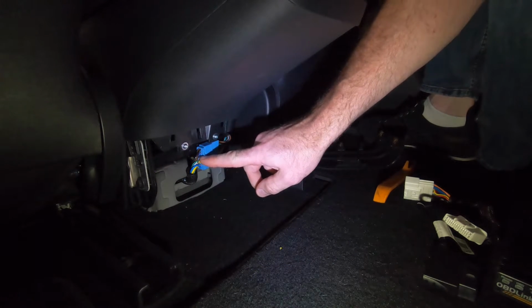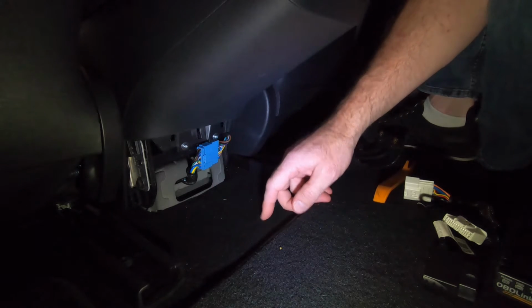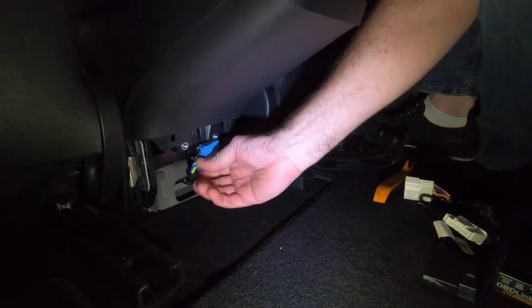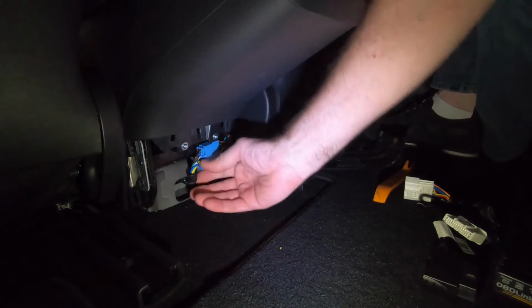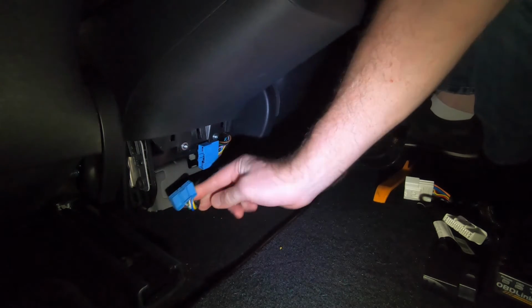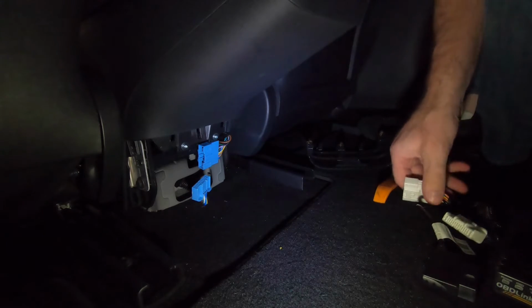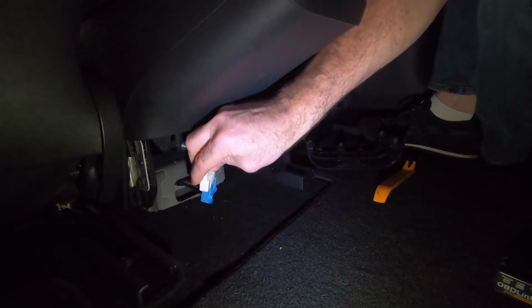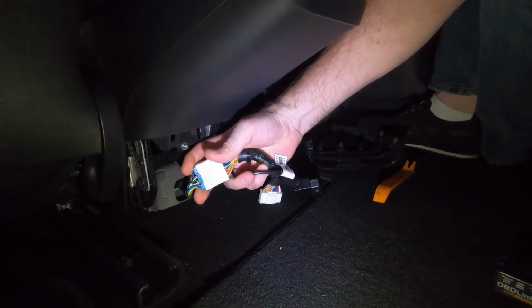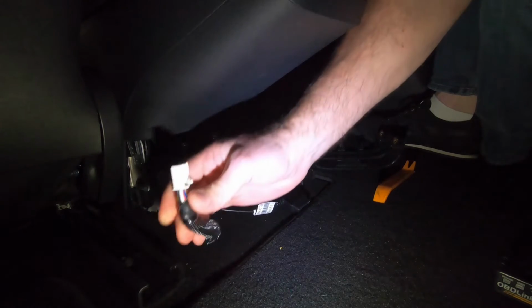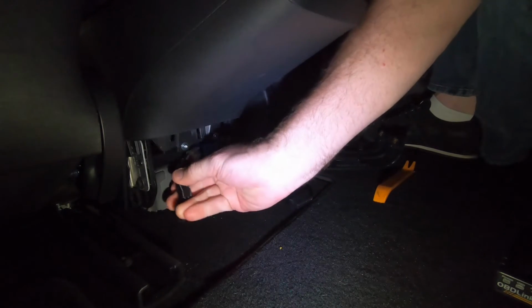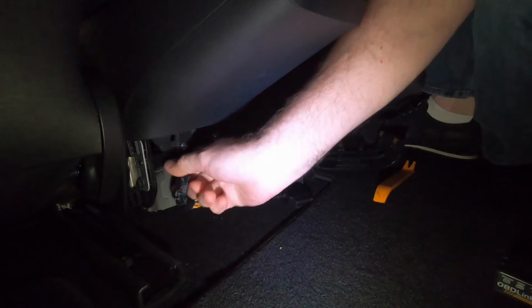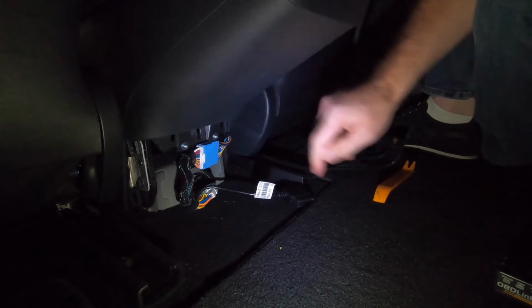So this is the harness plug that we want to undo now to tap into with our adapter. The car has powered down now, so we can just unclip. There's a little clip to push in here, so we push that clip in first, and the plug comes undone, it's that easy. Then we get our adapter plug and clip it in here. A nice click, make sure that's in all the way. Then we do the other end. Remember, we were clip facing outwards in the beginning. Make sure that's in secure, nice and tight.